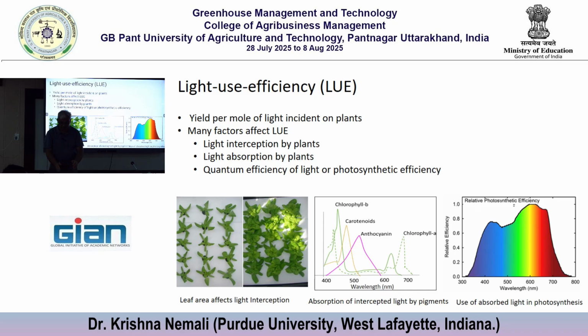Let's say you have a small plant. If I put the LED bar here, the light is going like this, and a lot of light is getting wasted when the plant is right here. But if I bring the bar down closer, the light is actually falling straight on the plant and the plants are getting a lot more light. So that advantage is there with LEDs. You can lower them to avoid such problems. You can either put more small plants in that area, or you can bring the LEDs down. You can't do that with high pressure sodium lamps.